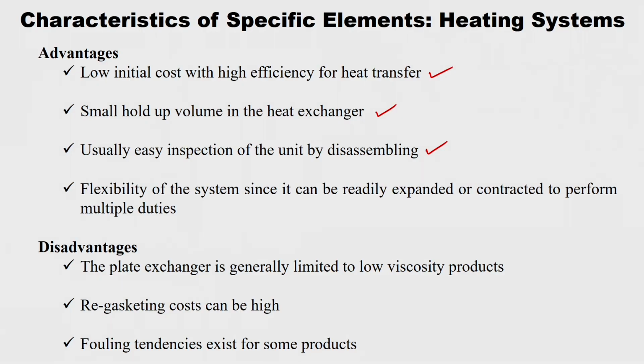The same heat exchanger, after some time I am using at the heating section, then I want to shift it to the cooling section. So I just have to remove or add plates based on the number required, and assemble them again. So this is the advantage. And there is flexibility of the system, since it can be readily expanded or contracted to perform multiple duties. So based on multiple duties I can add or remove the plates. So that is the main advantage.